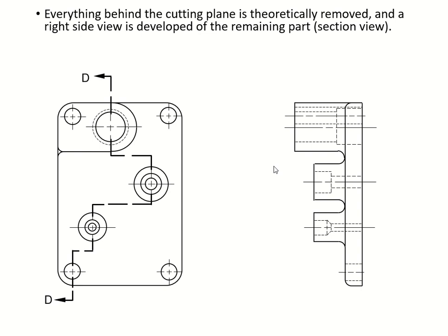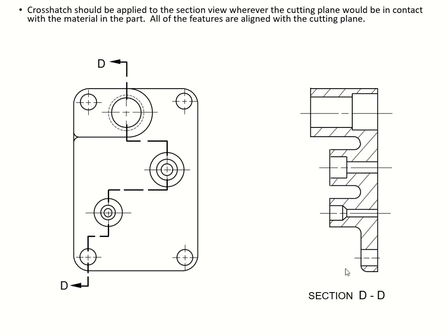Once you finish it, of course, this will be removed, and you will be exposed here and then here and then here and then here. So you go to each section, and everything that was hidden, just make it visible, meaning change the hidden dashed line into a regular continuous, thicker line.